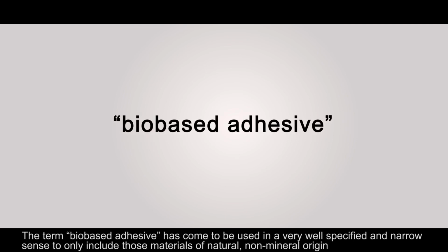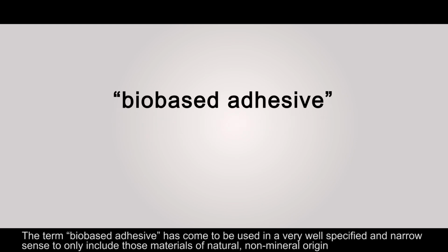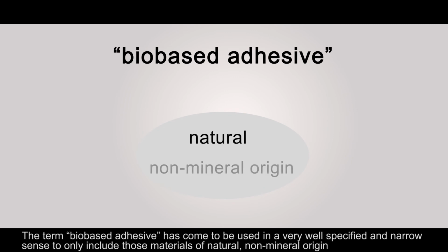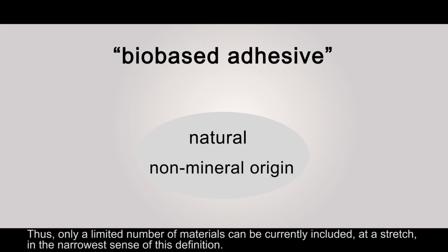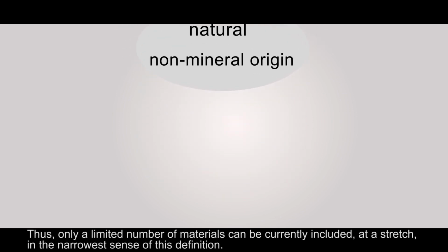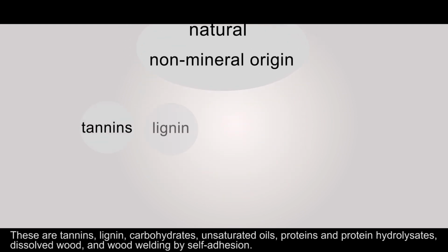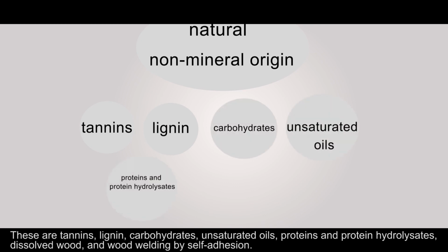The term bio-based adhesive has come to be used in a very well-specified and narrow sense to only include those materials of natural, non-mineral origin, which can be used as such or after small modifications to reproduce the behavior and performance of synthetic resins. Thus, only a limited number of materials can be currently included. These are tannins, lignin, carbohydrates, unsaturated oils, proteins and protein hydrolysates, dissolved wood, and wood welding by self-adhesion.